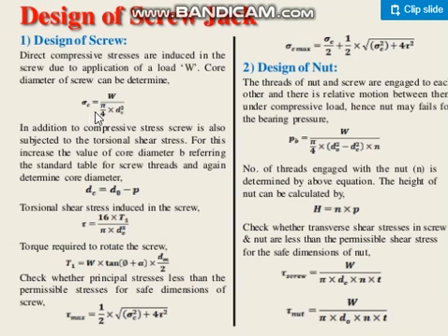Okay, and what is the resisting area for that compression? That is the least area. See, now we have three diameters. One is D0, which is the outside diameter, nominal diameter. Second is Dm, which is the mean diameter, and third is Dc, which is the core diameter. Which one we should take? Which of the three is small? The small will give you the smallest area. So it is Dc, which is the smallest. We have to take Dc here in this formula.